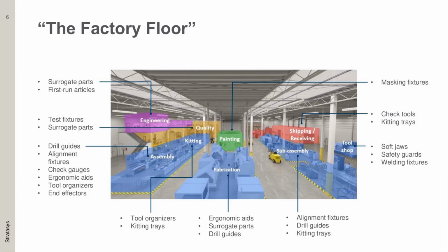Now, one of the things that additive manufacturing and specifically FDM can do is it can reduce a lot of these tooling pain points. You can design tools that are custom to the operator, and you don't need to worry about storing them in a warehouse because you can print the tools on demand. So oftentimes these tools can be printed in days or weeks versus months at a fraction of the cost, and they can be tailored to the product or the operator or both.